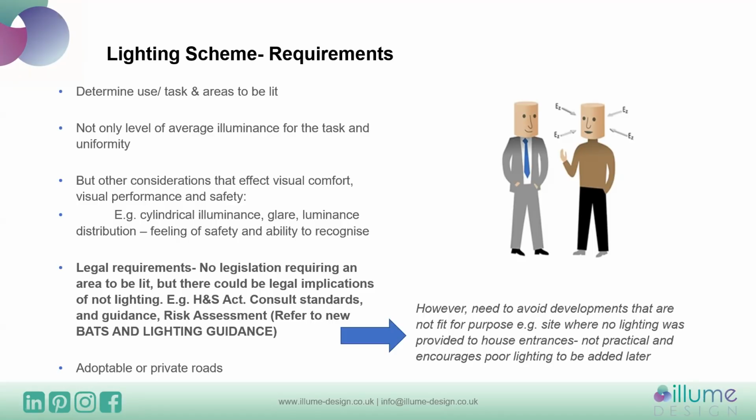Not only thinking about average illuminance for a task and uniformity, but also there's other considerations that affect people's visual comfort and how safe they feel in an area. And this can be to do with glare and contrast in an area from lighting, and also how well people can see each other's faces as they walk towards them at nighttime has a big impact on how people feel safe in an area. So that's kind of the lighting considerations, or some of them.